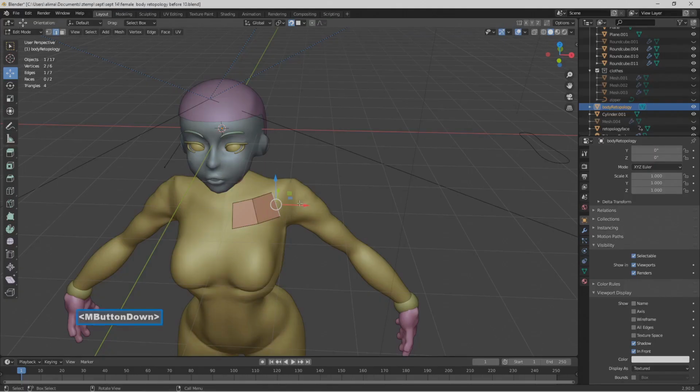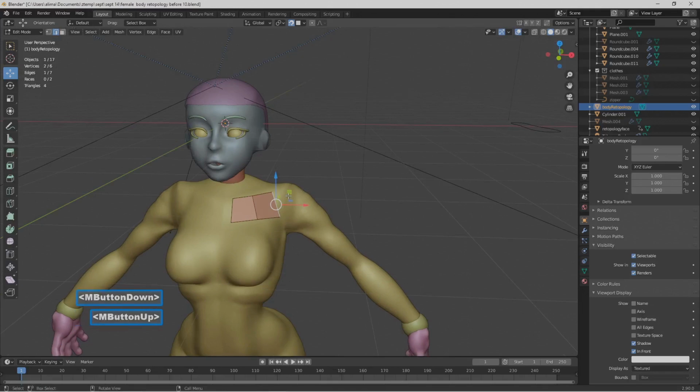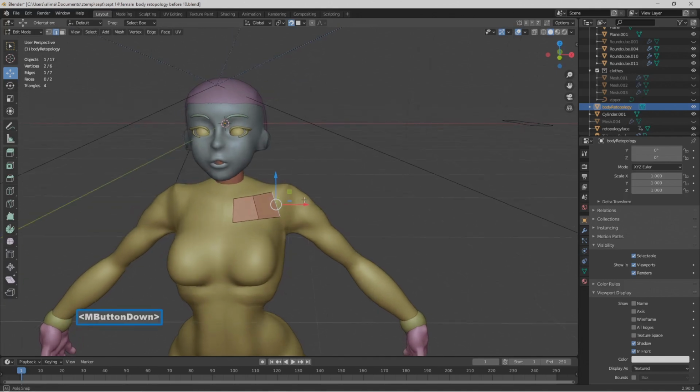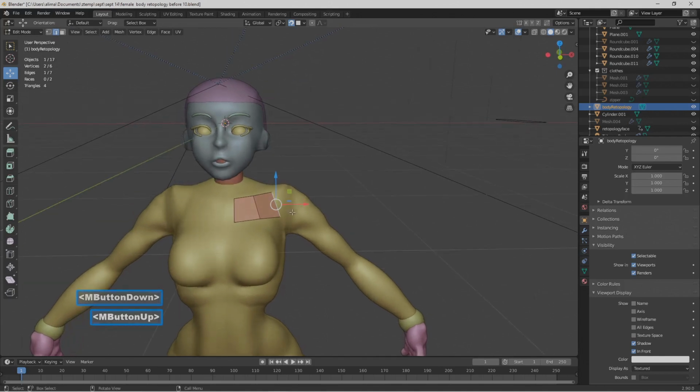Okay, these 3 pieces for the shoulder are going to be 1 face for the front, 1 face for the side, 1 face for the back of the shoulder. So I'm holding the middle mouse button to line up the view. The view is important because using this technique where we hold control then right click will set the angle of the face as well.